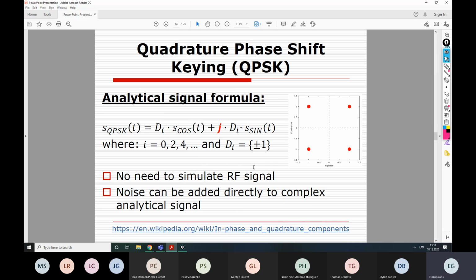And actually, additionally, we can represent this signal in a complex form, right? So we can even omit this, and that's exactly how we are going to do it in our practical exercise today, and work only with these voltage levels. We are no longer forced to simulate the carrier. If you remember, during our last work on the course project, for binary amplitude shift keying, binary phase shift keying, for BER estimation simulation, we created the harmonic signals, carriers, right? We performed the optimal receiving by calculating accordingly the voltage level and comparing it to some threshold, and nothing of that would be necessary if we were able to use the analytical signal form.